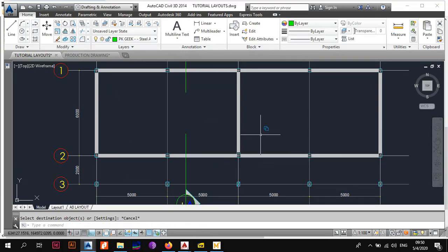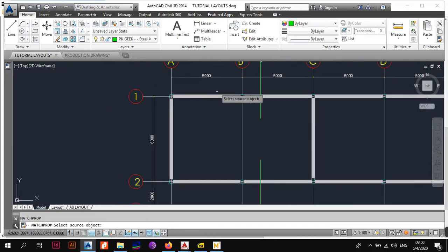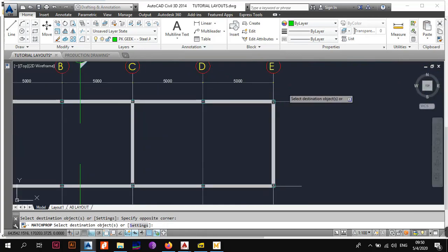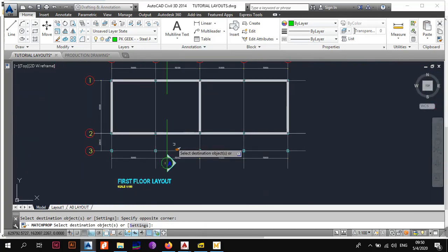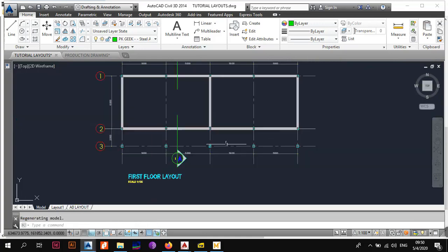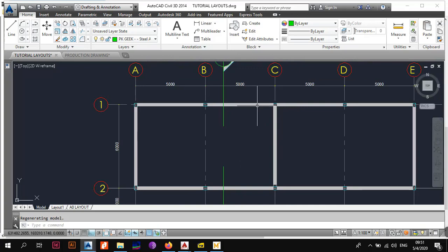The reason why we're changing it to a solid hatch is because a solid hatch represents anything that is below what you're representing. So to change back our grid lines, we're going to do this. And to make our things more visible, let's change the line scale with LTS. I'm just going to make it 500. Yes, as you can see now, the lines are much more visible. The differences in the lines are now clear to see.